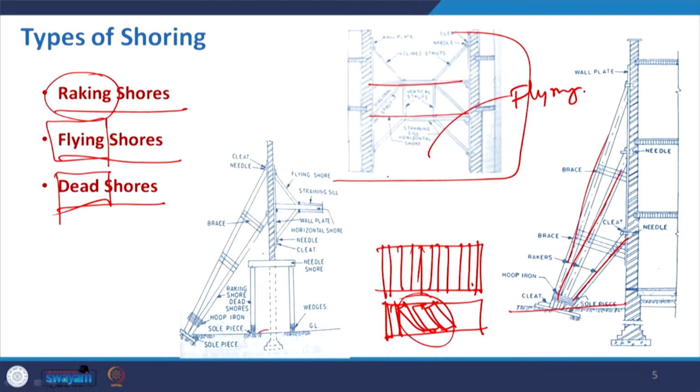The upper structure is supported with the racking while the foundation is being replaced. There is also another arrangement with vertical and horizontal members that gives support as a temporary foundation, and once the new foundation is made, we gradually remove this structure and make our structure safe again with that rebuild.